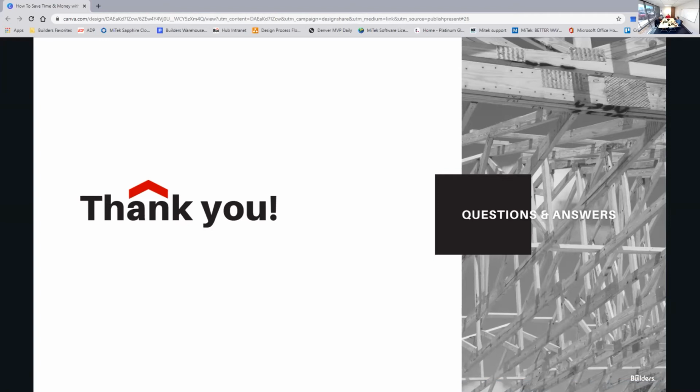Another savings that we've been taking a look at as well is applying Tyvek. We get into some challenges because the building inspectors can't see the nailing on the exterior wall application. So that's been an issue. We also are exploring the opportunity of spraying foam insulation in it. And so yes, we like to lead the industry in trying to bring whatever brings value to our contractors.